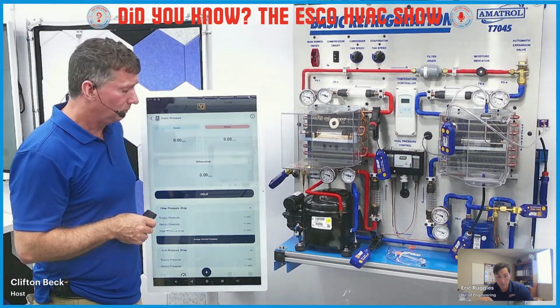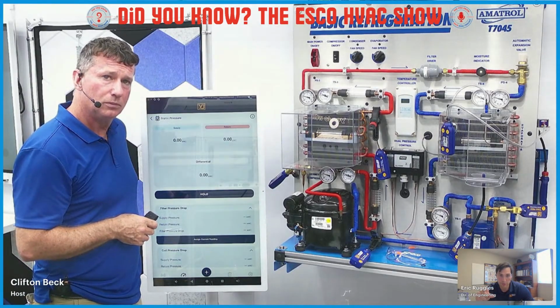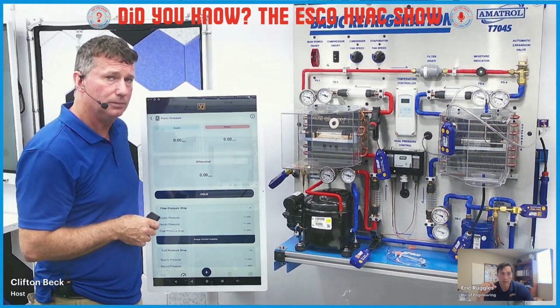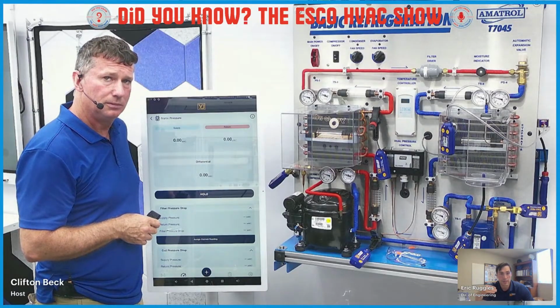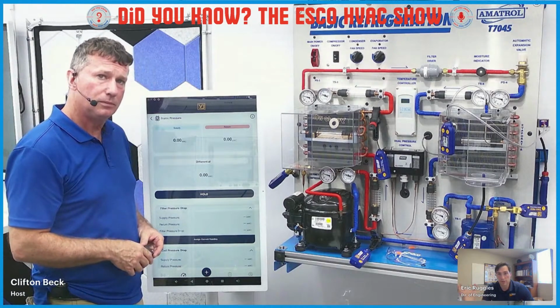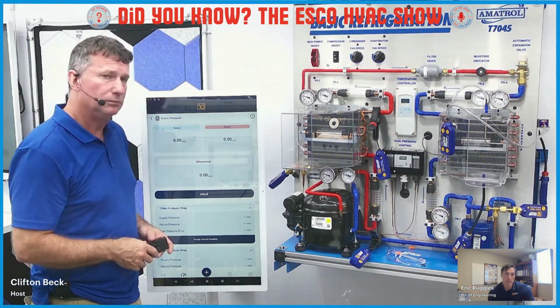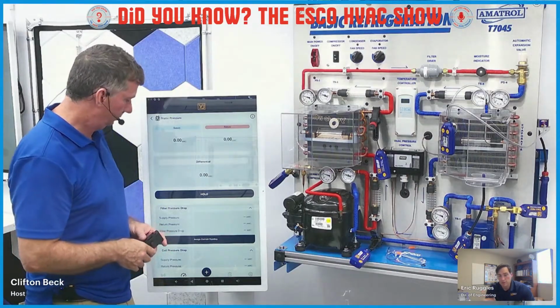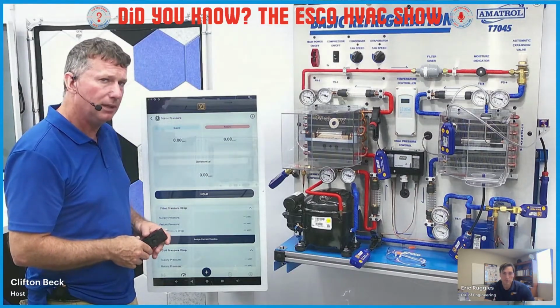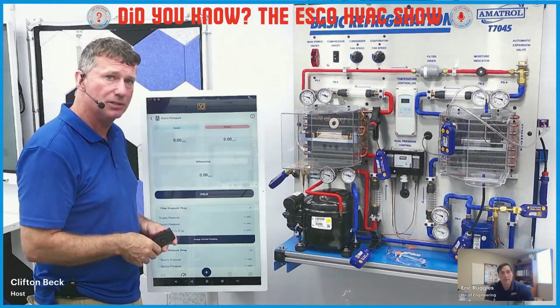We saved a few options in there, so you can hit hold on a reading and then scroll down and say, this is your filter pressure drop, or this is your coil pressure drop, or this is your total static pressure, and you can save those. And then you can, again, hit the plus sign, hit save to report or snapshot, and it'll automatically save those readings to your report that you saved. Love it. You can also use gas pressure and other readings on there.